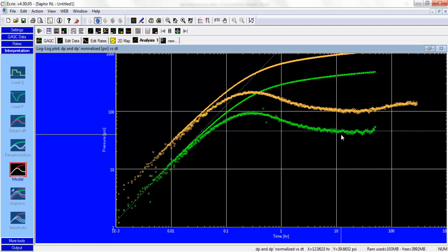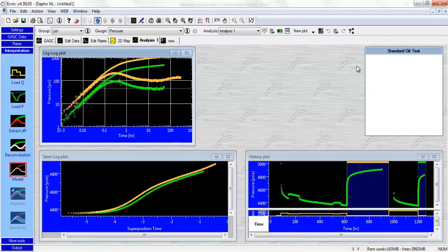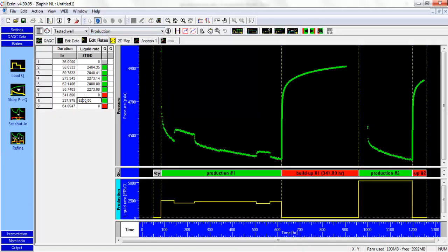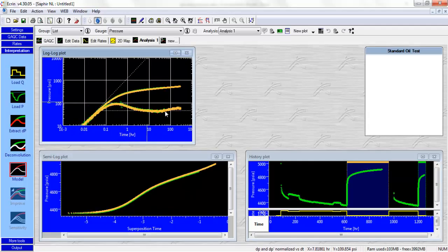You've got more information on this in the well test session called the main factors that complicate the well test analysis, but this is quickly to show you. Just by looking at the plot, you can QA/QC your rate history, and you can use this to estimate your rate data. This assumes that you don't have any other changes in the well performance, like gas breakout or things like this. So let's go back to edit rate and change directly on the table. We have 2200, and now again we've got our consistent derivative.